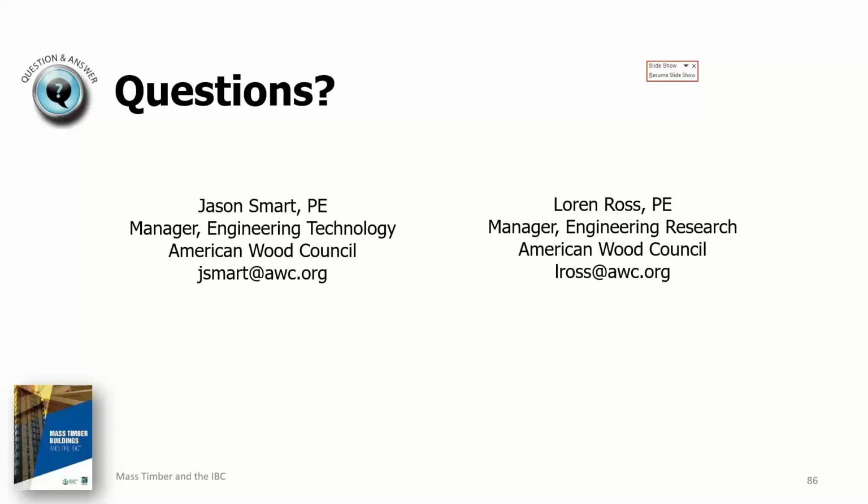All right, one last question. Intumescent paint, what's the story? Can we use intumescent paint for protecting exposed metal connectors and timber connections? Is that something that's in the code? Yes and no. It's not explicitly recognized, because of course, what do you mean by intumescent paint? Those are all proprietary. There's no standard intumescent paint, at least not with a recognized contribution to fire resistance ratings within the code, at least not like we have for Type X gypsum board. So in that respect, no.